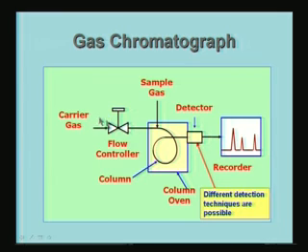The sample gas is going to be mixed with a carrier gas. The carrier gas flow is controlled by using a flow controller and a valve, and there is a source of carrier gas, usually a cylinder containing high pressure carrier gas, and of course, there should be a regulator, so that I can send it in at the required pressure, and it goes through the flow controller, and the amount of flow is controlled by that.